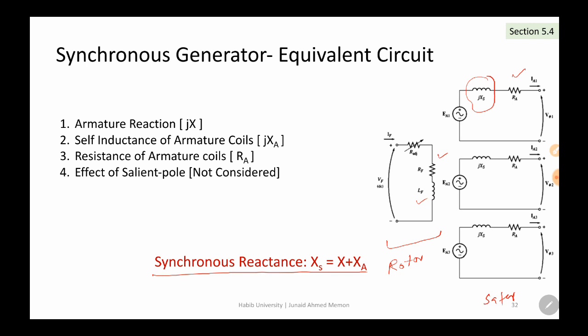Now, we have the three phase windings, the output windings. You want to supply the three phase voltage to the output, whether to the consumer or someone else. You can give each phase individually, but generally three phase windings are connected into the Y or the delta fashion, as you know.